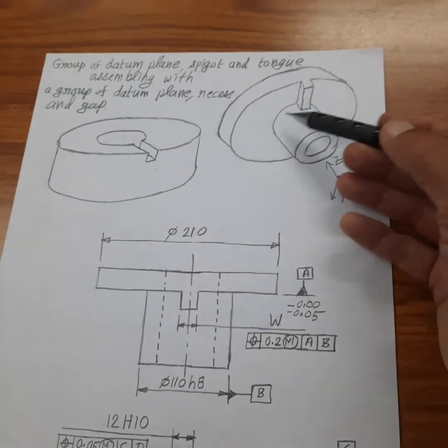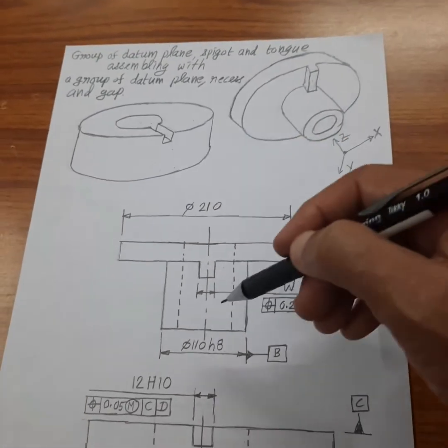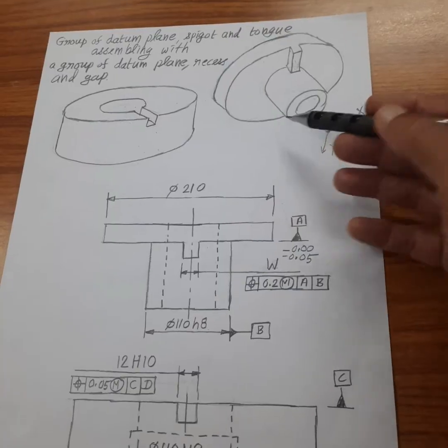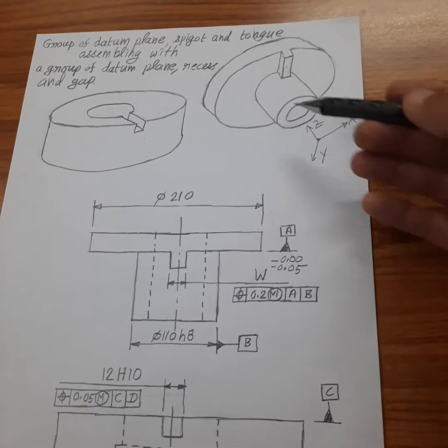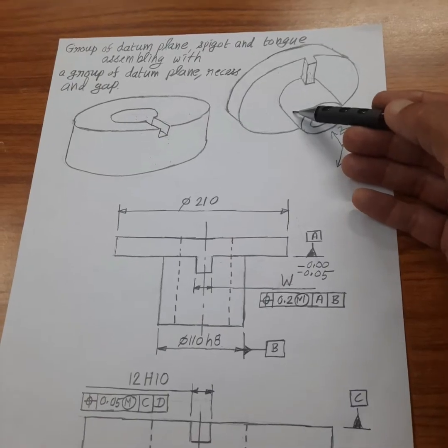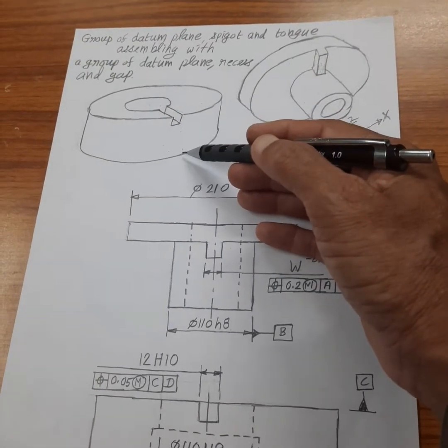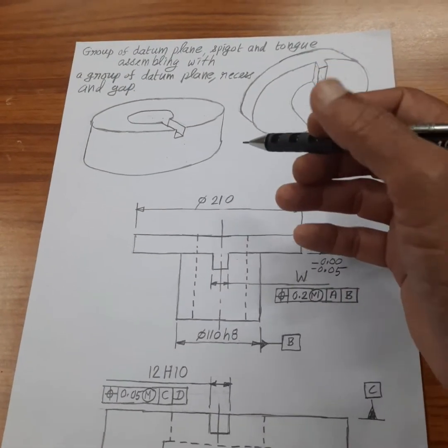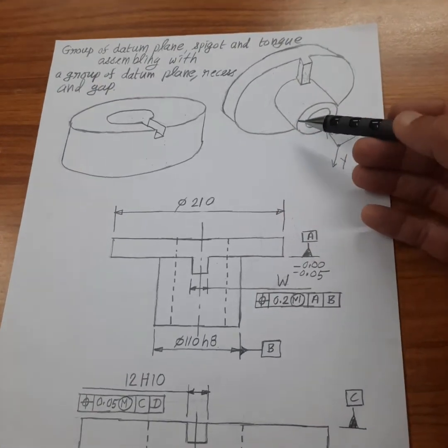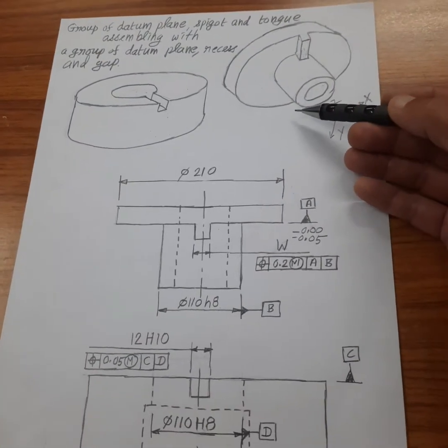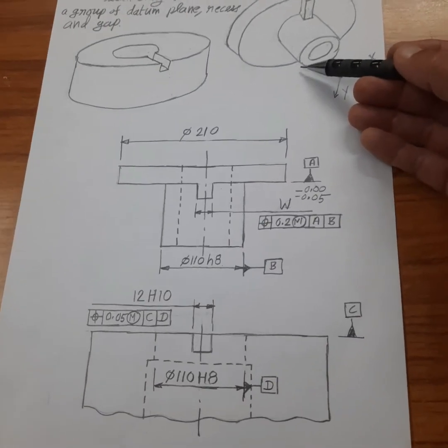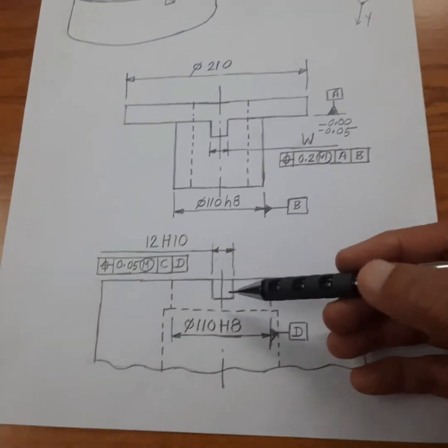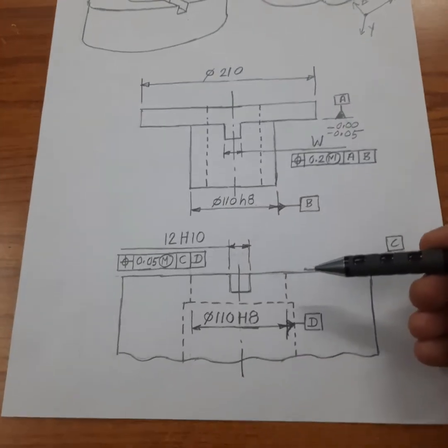Due to this clearance, the rotational degree of freedom of this member about the z-axis is not fully constrained. So you can still rotate this component a little bit after inserting it into the bottom component, not fully. So that calls for locational inaccuracy in rotation. We have to determine these 2 locational inaccuracies using the values given in this example.